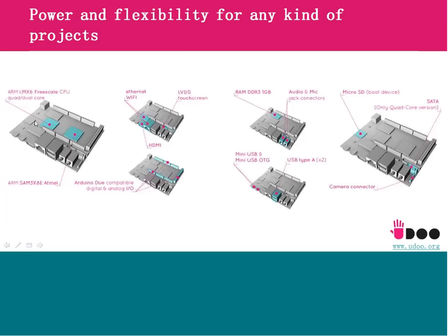And the main processor, the Linux one, is an i.MX6 processor from Freescale. It comes in dual or quad core, and they share both GPIOs. So you can access the GPIOs both on the i.MX side or from the Arduino side, from the SAM3X. So basically, this is the microcontroller of the board. I hope this was your question.